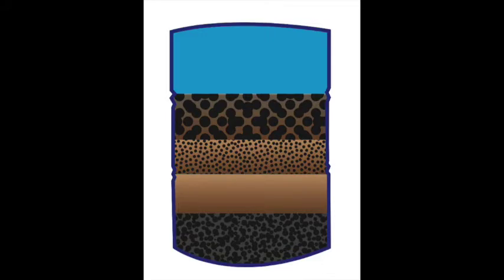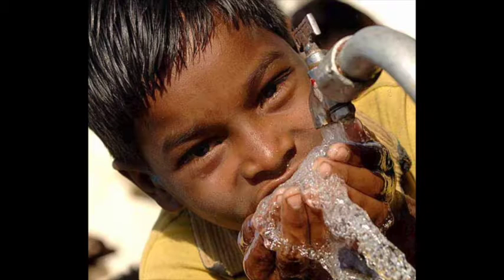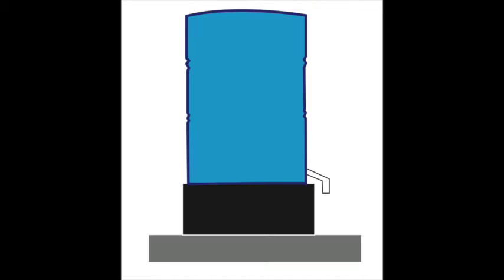We will start with a contained vessel filled with 4 layers of filterable media to remove harmful impurities and improve the aesthetics of the water. As mentioned before, the remaining bacteria can be eliminated through boiling or leaving it in the sun for a couple days. This last step is critical for drinking water provided to small children, who are very susceptible to waterborne pathogens. We envision our system to serve smaller villages, around 1,500 people.